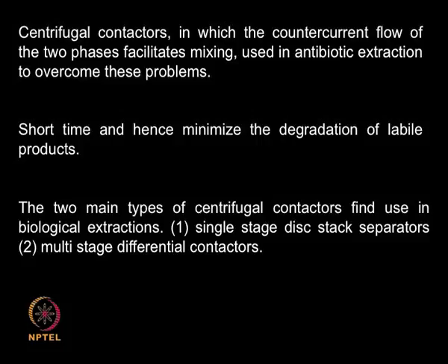So if the density difference is very low, instead of resorting to the normal extractors which I talked about in the previous class, column extractors or agitated extractors, we may even go to centrifugal contactors. Nowadays there is a lot of interest in liquid centrifuges, whereas the normal centrifuge we are used to is a solid liquid centrifuge, where you are trying to remove the solid or filter the solid out using a centrifuge. But here we are talking about a liquid centrifuge, and the density difference creates the separation.